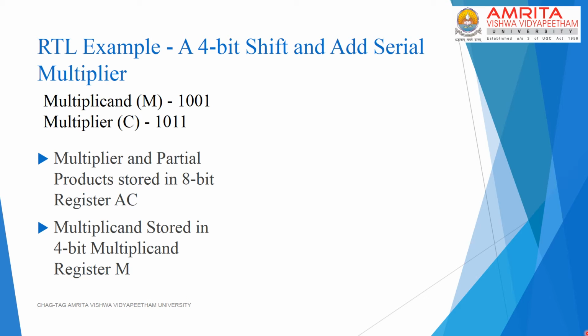The multiplicand is assumed to be stored in a 5-bit register. A second register called the accumulator is a shift register, which is initially loaded with the multiplier in its least significant bit positions and zeros in the position which will be storing the partial product during the course of the multiplication sequence. The generation of the partial product will depend on the current multiplier bit.